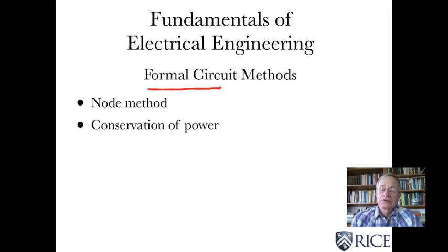So instead of going back to the VI relations, KVL and KCL, and solving a load of equations, we're going to develop something called the node method, which very efficiently uses the VI relations, KVL and KCL. Turns out it's so efficient that you may want to use it to check your answers that you get by other techniques. It's very nice and very general. One of the surprises is that you can use the node method to prove that circuits conserve power. The assumptions underlying that proof are pretty interesting, and we'll see how that works out. But first, a circuit that's a little harder than it looks.